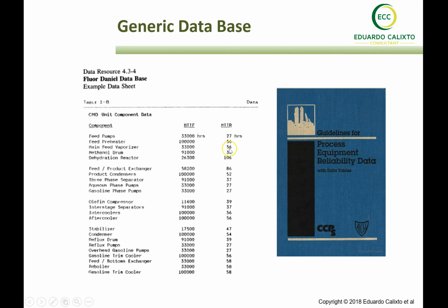So we just need to be sure that this time of each equipment represents all this real downtime, considering the time to open the equipment, inspect, detect the failures, as well as to close the equipment. Okay, so we need to check this downtime. But here, for example, you can see that to repair a reactor, we need 106 hours. For me, that is realistic information.